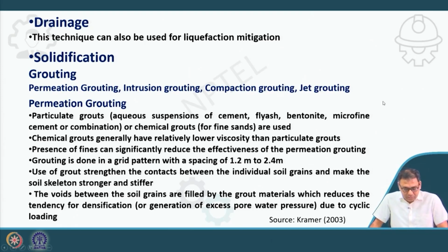The chemical grouts generally have relatively lower viscosity than the particulate grouts. The presence of fines can significantly reduce the effectiveness of permeation grouting. So we remember that the presence of these fines can reduce the effectiveness of this permeation grouting technique.